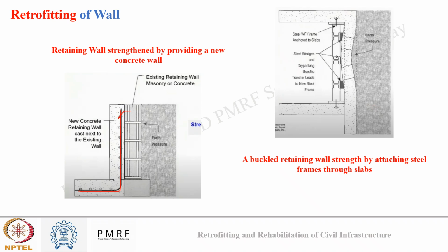This is a shear collar like pattern, which runs inside the old concrete and locks the new concrete with the old concrete, so that when the load is acting on the structure, it is properly transferred between the two. So it is very important that when I'm placing a new concrete overlay over my old concrete, both the concretes shall be connected properly. So this is one way.